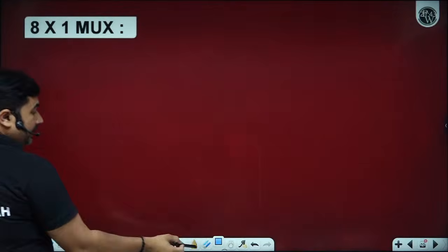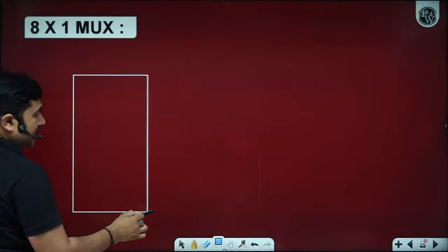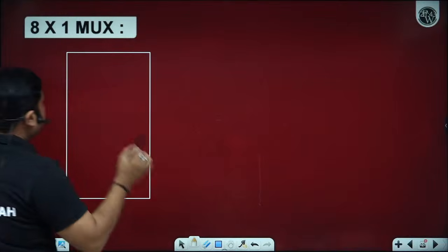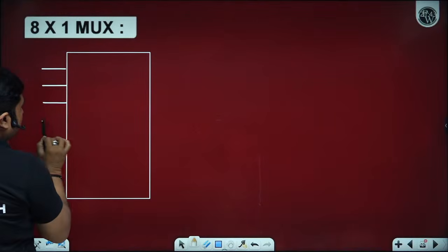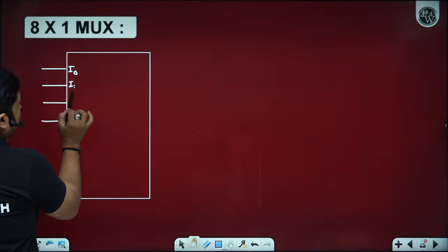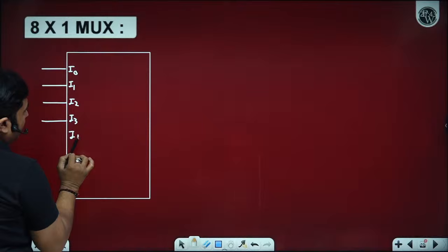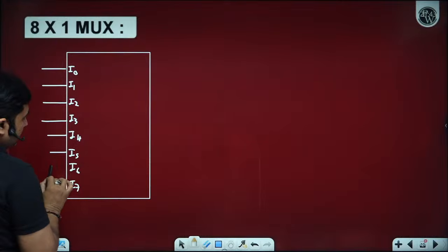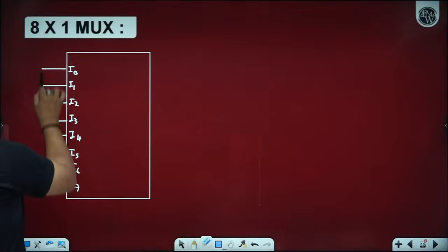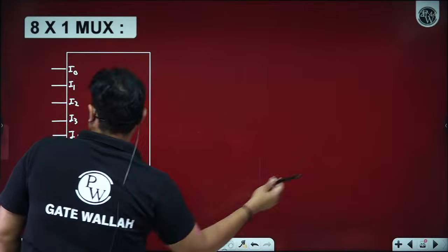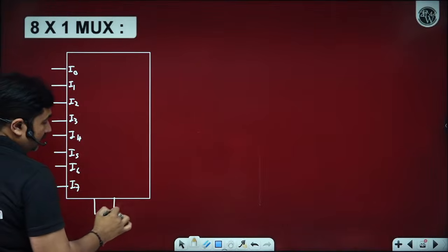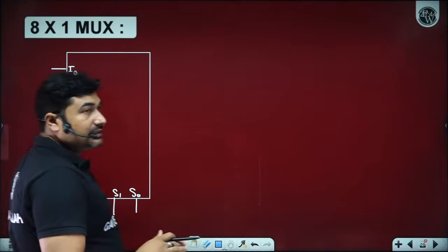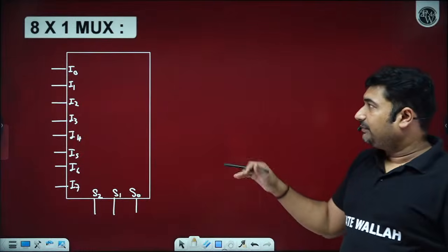Yes, sir. We are able to understand the internal circuitry of 8 cross 1 as well. In an 8 cross 1, we have I0, I1, I2, I3, I4, I5, I6 and I7. Okay. Yes, sir. So if we talk about 8 cross 1 mux, then S0, S1 and S2. Depending upon the select lines, one of the inputs is transferred to output Y.